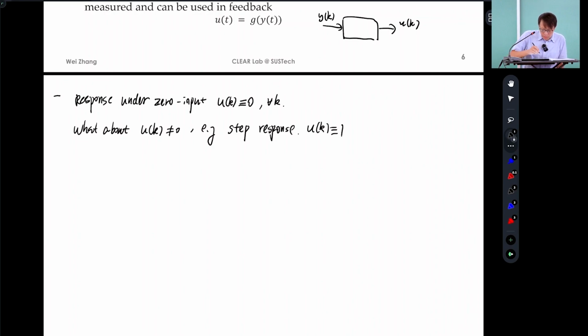In this case, we have learned the state space trajectory solution. The zero input response is A raised to the power k times the initial state, the response mainly due to a non-zero initial state, plus the zero state response, the response mainly due to input without any initial condition.